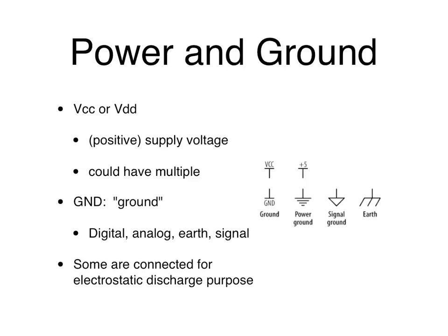Since we're talking more about the electrical level, first you have to have the different voltages, right? So ground versus supply power. There are different kinds of ground. A generic one might just say GND. Then there's power ground, which you draw with these horizontal wires. Signal ground is what you might see a little bit more. That's what general purpose I/O ports deal with.